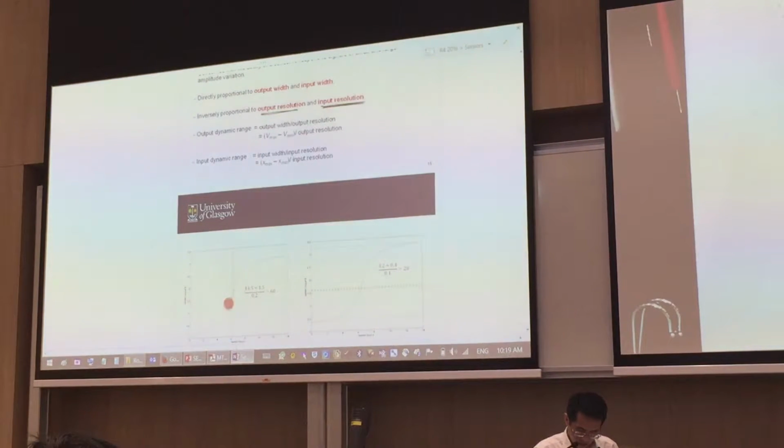This is your nonlinear static response. Right? The static response here again means that it doesn't change at any point of time. It's static response. If it changes over time, you may experience drift. Right? So that one we call a dynamic response curve. So for a static response curve, the output resolution, for example, in this case, this one will be your output. So this amount of resolution, meaning the smallest amount that you can differentiate when there is a change.